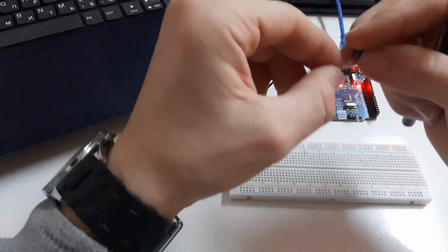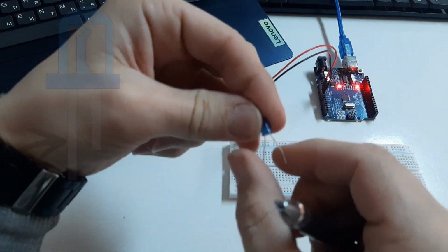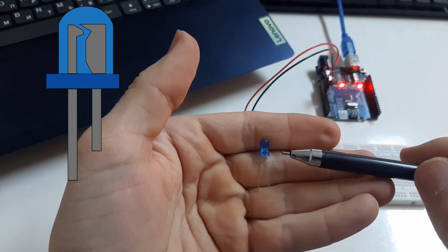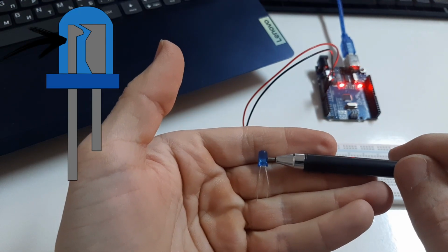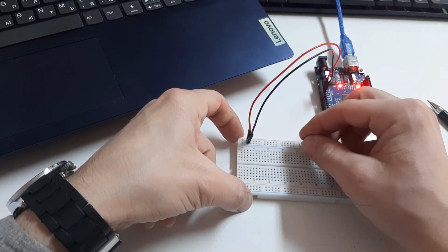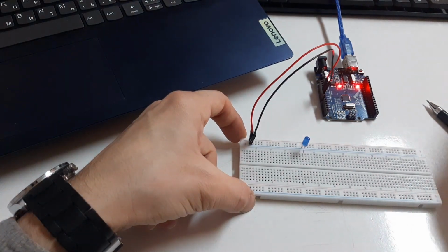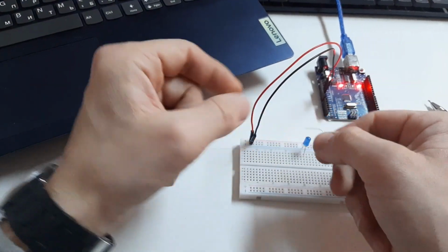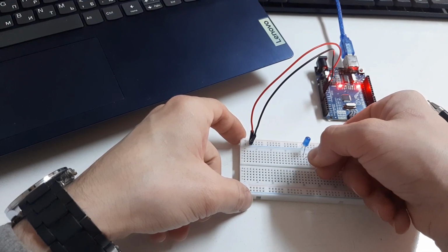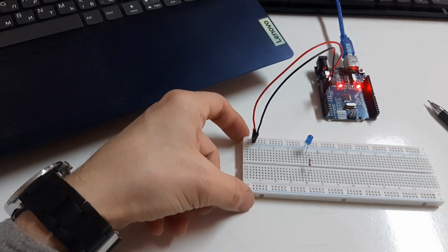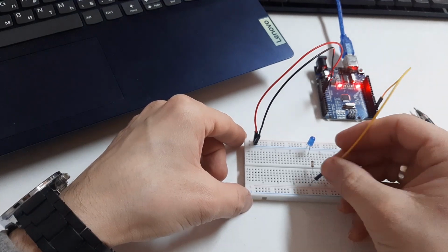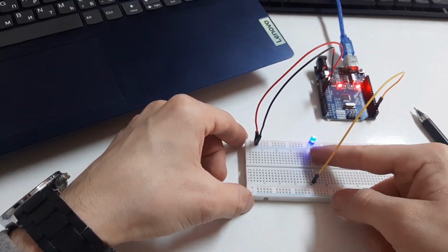When connecting the LED to the circuit we must pay attention to the positive and negative legs. If the legs are uncut, the longer leg is always the positive line. If the legs are the same length, the smaller part inside indicates the plus line. I connect the minus leg of the LED to the minus line from the Arduino to the breadboard. The plus leg enters one of the 5 holes below. We also transfer the energy through the resistor to the LED so that the LED is not damaged. We take the plus line from digital pin number 2 and connect it to the resistor. Yes, the LED is on because there is energy on pin number 2.